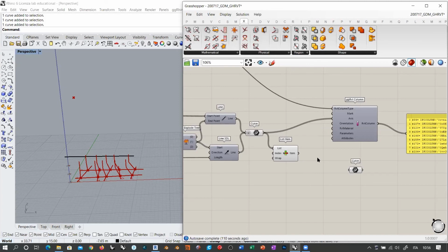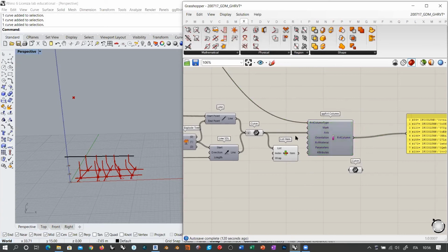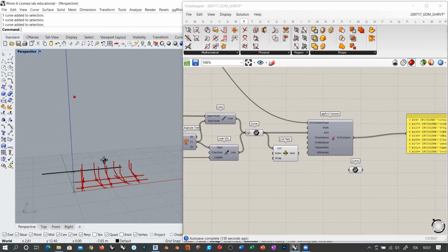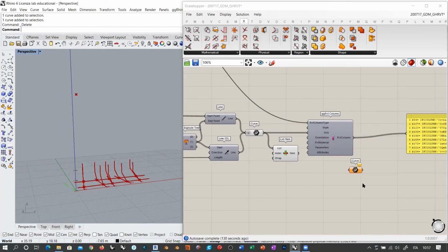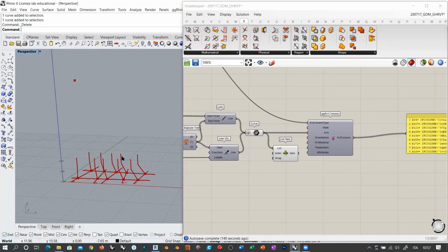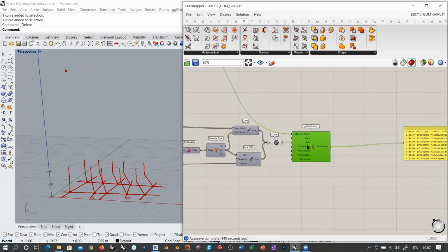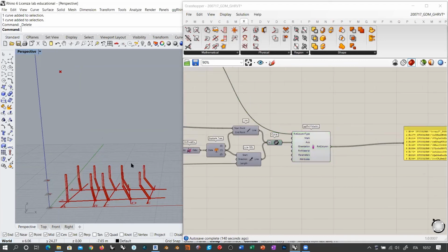So if I import the IFC file in Revit and make some changes, and I re-import the IFC, all the changes get lost. Of course, there are ways of avoiding this kind of side effect, and we will see how this can be managed. But nevertheless, this is very useful when you want to make some design changes controlled with Rhino and Grasshopper techniques. Okay, so pay attention to this.